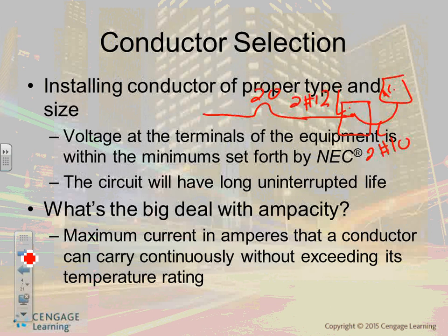But what the violation is, the equipment here, if you read on the nameplate, it says an overcurrent protection device of 30 amps. But if you read it clearly, it says maximum. It says maximum. So can you go lower than 30 amps? Yes. So technically, he really did not violate anything other than the normal wiring methods, which we typically throw a 30 amps on it. So no violation of the code because this says max. If you go ahead and put 5 amps if you want, it's not going to work, but it's safe. It'll trip all the time. So anyway, I thought that was interesting.